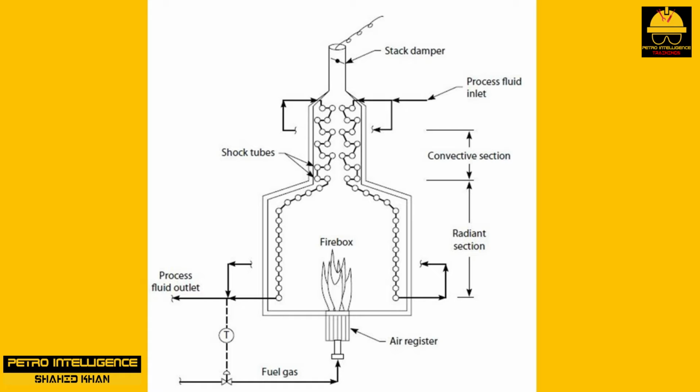This sets the heater up for afterburn in the stack, and the heating value of the fuel is also effectively reduced. Allowing a fired heater, boiler, or furnace to operate with insufficient air is hazardous because the products of incomplete combustion are hot and will ignite as soon as they find sufficient oxygen.